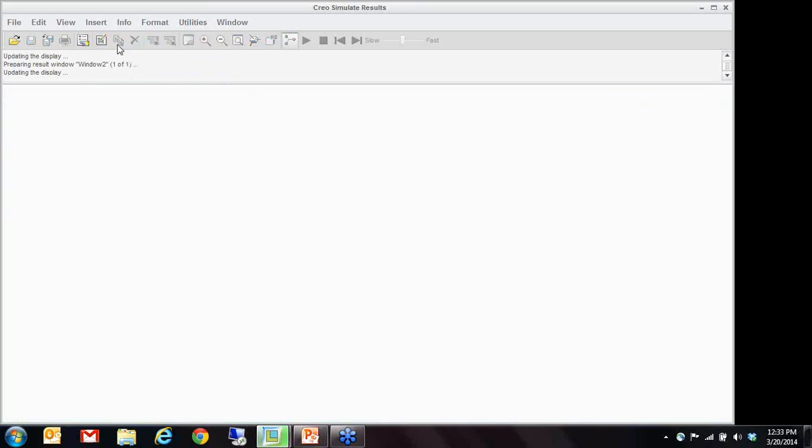That's the difference between copying an existing results window and changing the quantity, format, whatever you want, or inserting a brand new results window where you can compare two parts side by side. Now why would you do that? Now let's say I'm working on a design, you worked on a different design, I want to compare the results of both these different designs side by side, I can choose to do that.